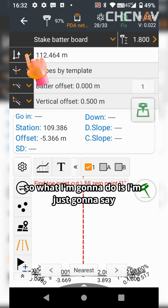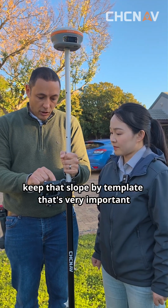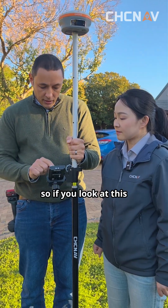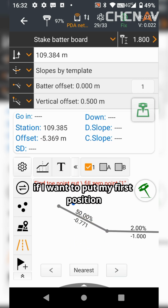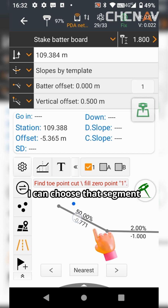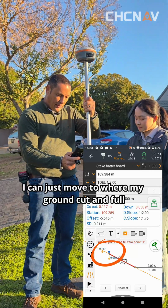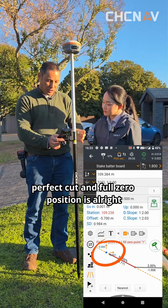So what I'm going to do is I'm just going to say I want my current station. Next, I will have to keep that slope by template. That's very important. And then the next step, batter offset. So if you look at this cross section here, we are currently at that position. Yes. If I want to put my first position at the toe where the ground intersects that specific point, I can choose that segment. Yes. And now you see as I move out, I can just move to where my ground cut and fill, perfect cut and fill zero position is.